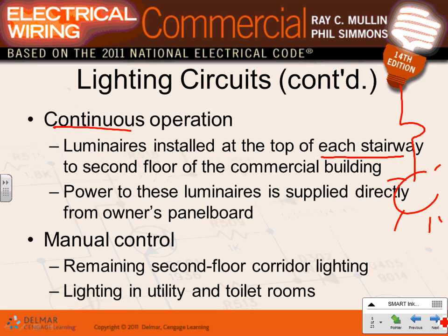Again, it's not really in line with the energy code now. You have to dim them or do something with them. For security reasons, sometimes stairways are also kept on at all times. So if you have a stairway, a good application is to keep the lights on. So the light is directly powered through a circuit breaker, no switch. Can I have a thumbs up, Chad? No switch? Got it.